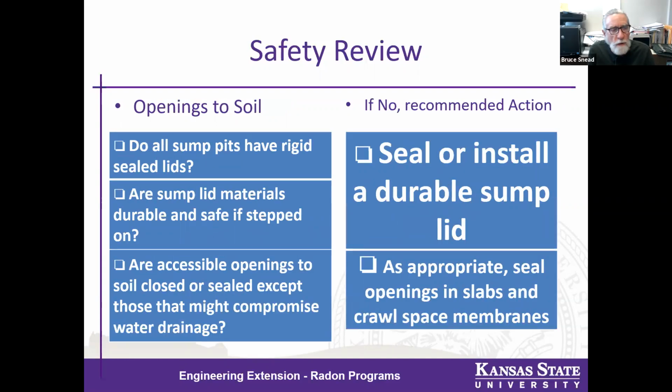Openings to the soil that allow radon to enter. Do all sump pumps have rigid sealed lids? Are they well sealed? Are accessible openings to the soil closed and sealed except for those that might compromise water drainage? And if the lid is not properly sealed, it should be repaired or replaced. And certainly any accessible openings to the soil should be sealed as part of the standards.